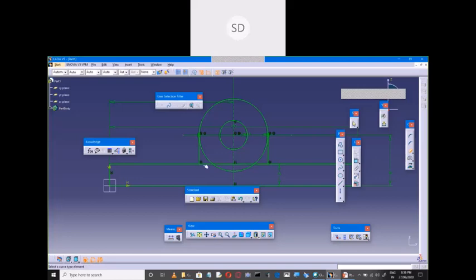You just double click if you want to activate it in a continuous manner. Okay, your diagram is over. Now in this case, as it's showing with a continuously green line, then the diagram is completely constrained. That means it is perfect. There are no deficient dimensions, and it has no over constraint.